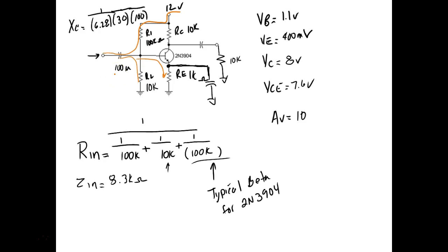So at 30 hertz, but think about it, we're going to operate this thing higher. Let's say 1,000 hertz. This guy right here has almost no opposition to 1,000 hertz. It's going to be 1,000ths of 53 ohms, so it's in the milliohm range, right? So here comes my AC signal. It can either go through that 1K resistor, or 99.9% of it is going to fly over and go around through that capacitor. This guy right here, we call it a bypass capacitor. Now my DC bias still has to go through the resistor, so it blocks the DC bias, but allows the AC signal to go around.